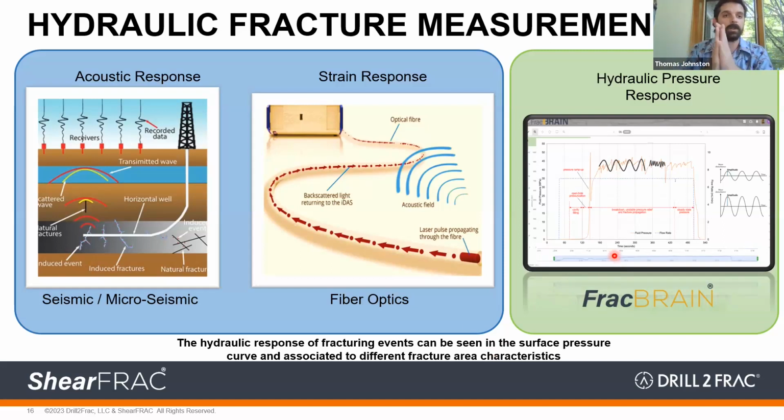If you're pushing on a rock and pushing on a rock and the pressure is increasing, you're not breaking it. If you create a large tensile planar fracture, fluid's going to rush into it. You're going to get a big drop off in pressure and a long time to build it back up. So you can interpret these different ways of the rock breaking down, whether they're large or small breaks. From that, you get a really accurate measurement of fracture surface area in real time. And when I say real time, I mean it's literally popping up in front of you so that you can react to it and work along with it.